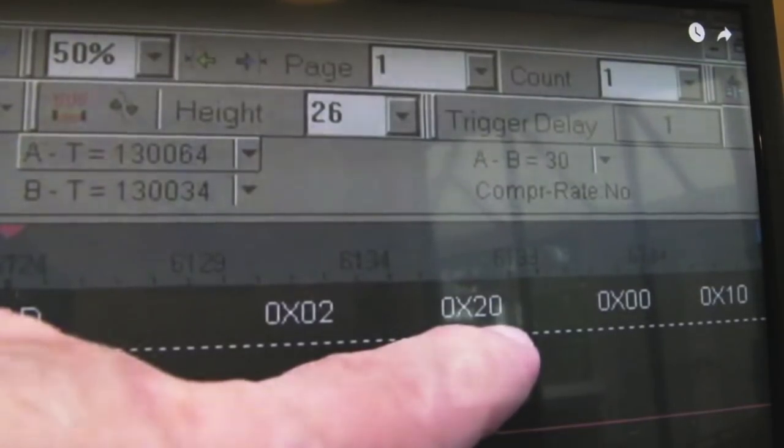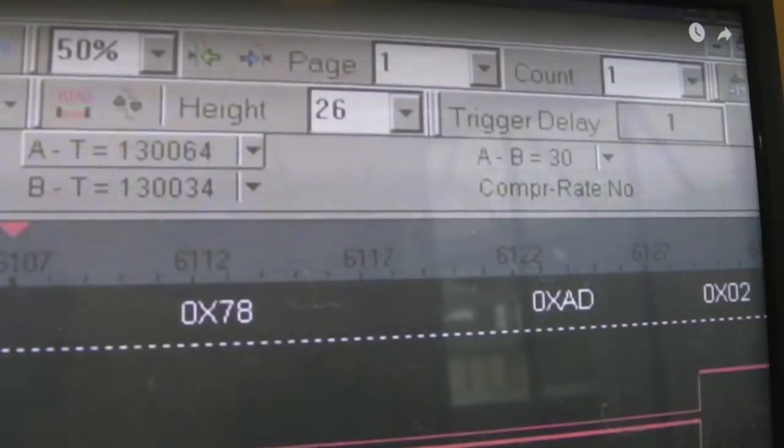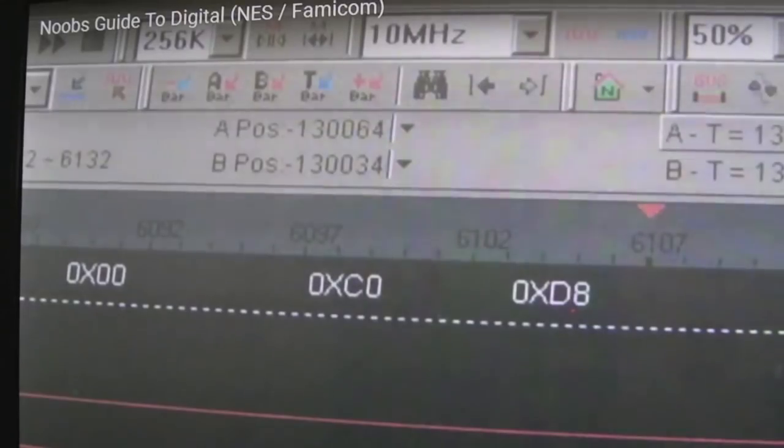I think Chris was pointing out that the CPU was doing something with the program counter and the stack and stuff, although apparently the stack can't be written to at that point because the write pin is held high during reset. But it was interesting that I'd missed out on that. I didn't think of that. The reset part I wasn't aware of, to be honest. I wasn't aware that the CPU did anything whilst it was coming out of reset, so that was news to me. But the part where it reads the reset vector, if we just step back one, there you go, you can see the reset vector there, C000.